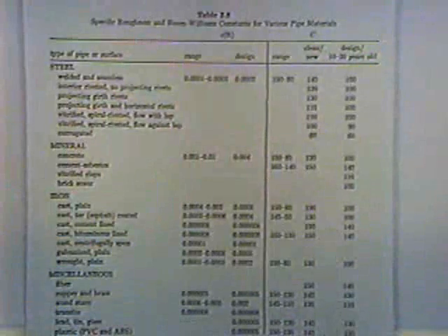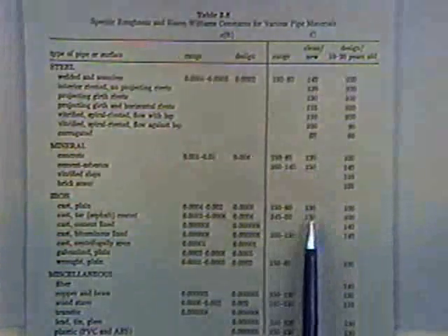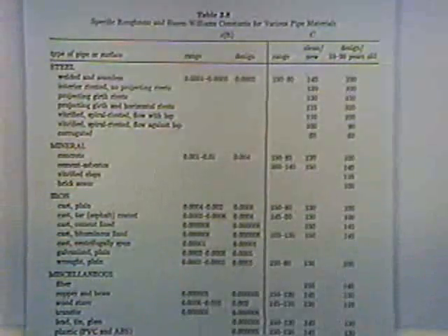And so we plug in the numbers. Hey, small question for you. Yes. Somehow, when I look it up in the book, I get a C of 130. Okay. I just don't know if there are different tables. I mean, I know this is a small point, except I just wonder. No, good point. And by looking up in the book, you're referring to table 3.8. Right. And you're saying that for the cast iron pipe, it says the range is between 150 and 80, which is a tremendous range. For a clean new pipe, it's 130.